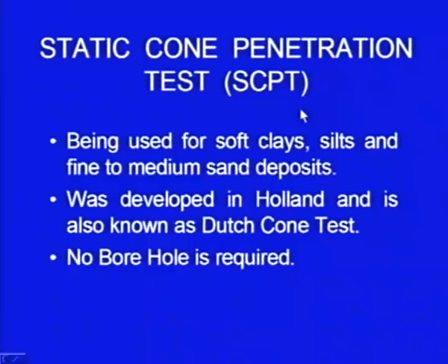The penetration resistance is found out, and that penetration resistance is correlated with the soil properties. Now, this test is quite popular now, it is being used for soft clays, silts and fine to medium sand deposits, and at many places it is now replacing the standard penetration test.